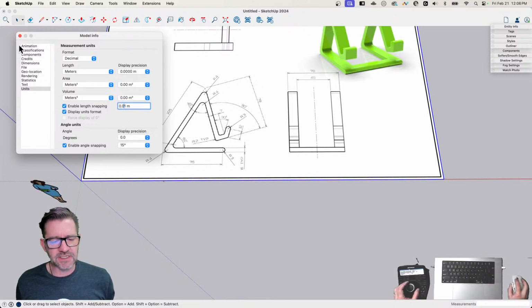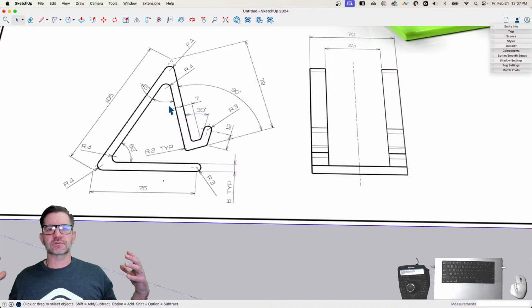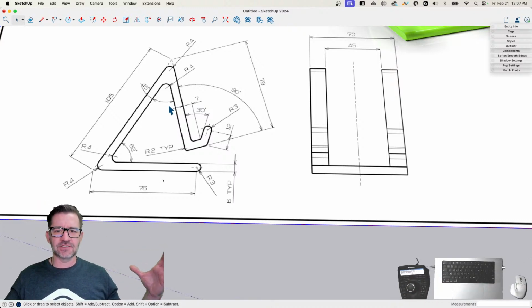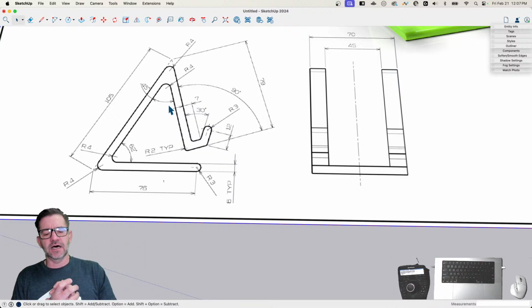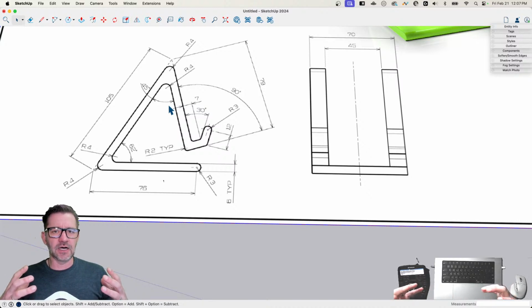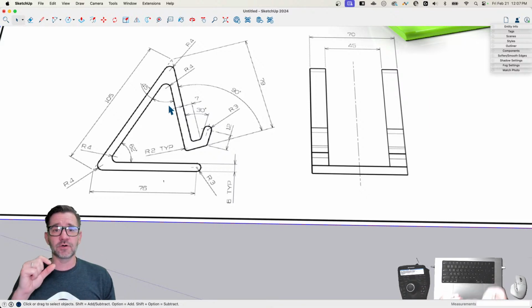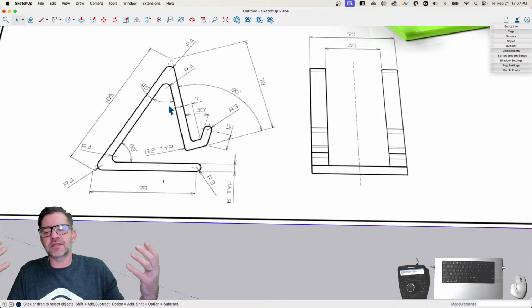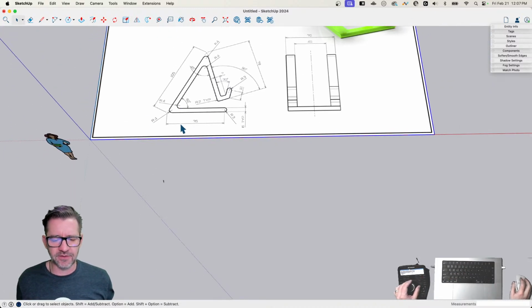The reason I draw in meters instead of, I'm assuming, millimeters, is SketchUp is created to draw house-size objects. These are obviously much smaller than house-size objects. All of these objects we're creating will fit in the palm of your hand, and it doesn't always do an amazing job with real tight, small faces. SketchUp can actually support models with very, very small faces. It has a hard time drawing them, though. So we're going to draw this at meter scale. And then in theory, if I wanted to 3D print one of these parts, I could take it and scale it down and then print it out at proper scale. So we're going to draw everything here as meters.